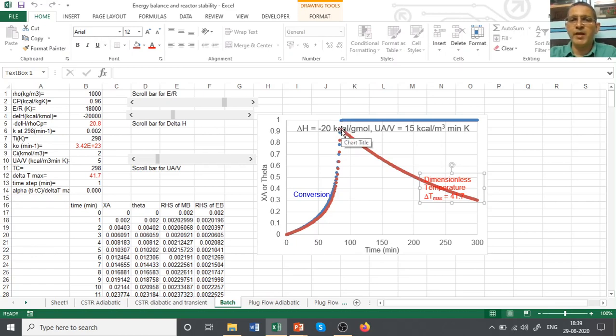Peak temperature is very high, and predicting this peak and the value of that peak is very critical because our product may be heat sensitive. It may start decomposing. It may reach auto ignition temperature of the solvent. Whole reactor just catches, explodes, fire, right? Safety considerations, these are very, very important.